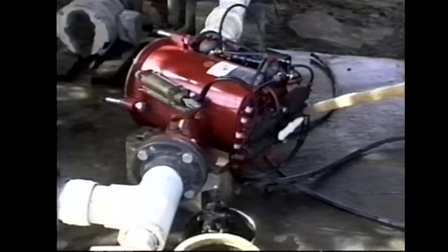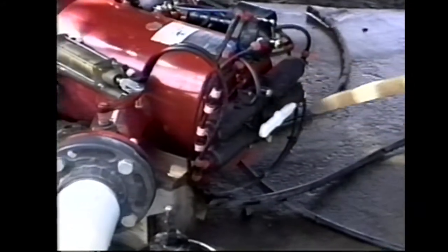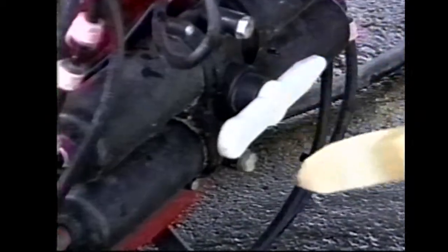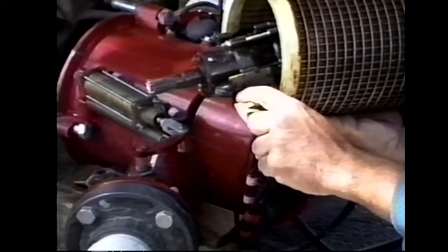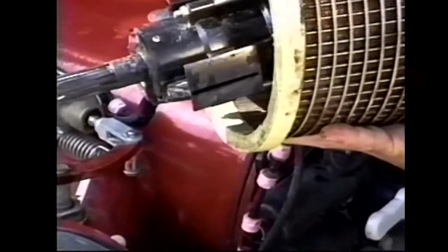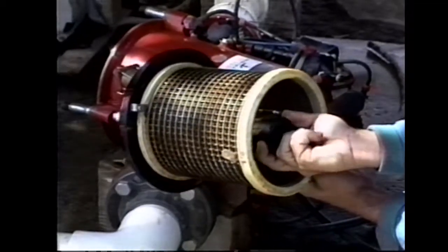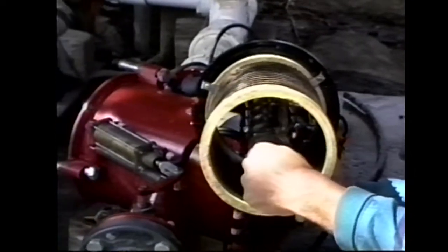Simultaneously, the rotating arm or suction scanner is activated and makes one very slow revolution. The suction scanner fits inside a 120 mesh tubular screen. Clean water flows backwards through the screen into the scanner ports and cleans the screen surface. The scanner has only a 1/32 inch clearance from the screen. The irrigation water continues to be filtered during the cleaning process.